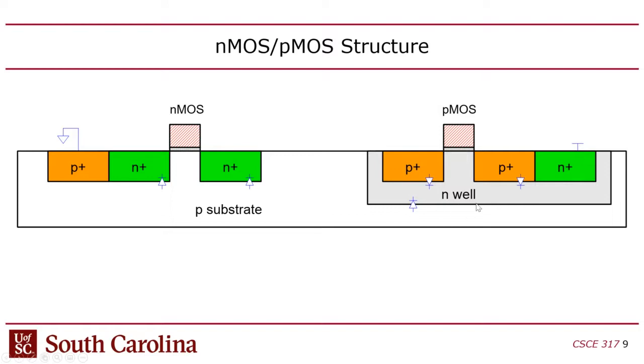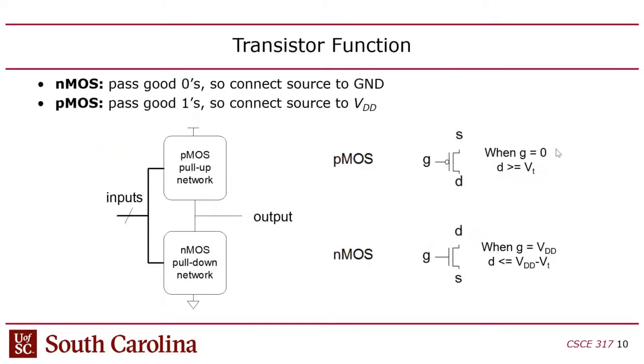The same thing applies to the N well. To get the N well connected to a wire, which is going to be your VDD, your power supply, you don't want to go straight from metal into N well, because the N well is not very conductive, since it's not doped very highly. But if you have this highly doped N-type silicon as an interface, the VDD metal wire goes down through a via, connects to the highly doped N, and then that transitions down to the lightly doped N. That's generally how these transistors are designed. That part's not as important. That's only important if you're actually doing layout, and we're not going to talk about layout in this course. But I just want to point it out because it's in this diagram.